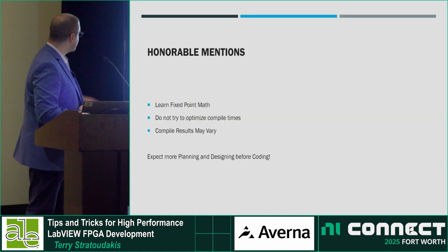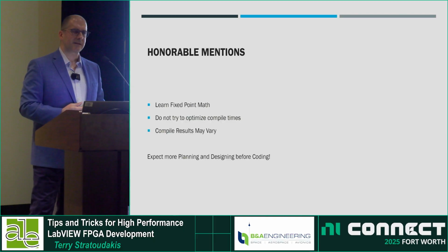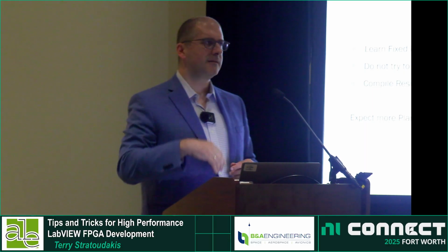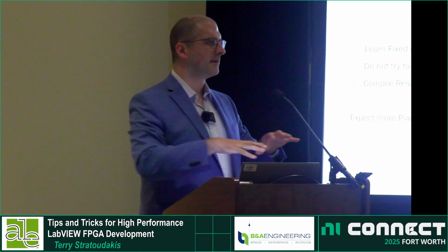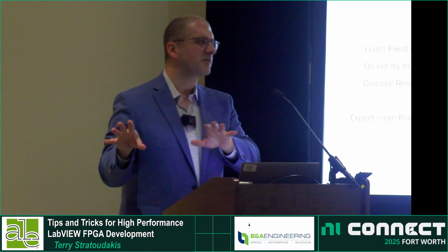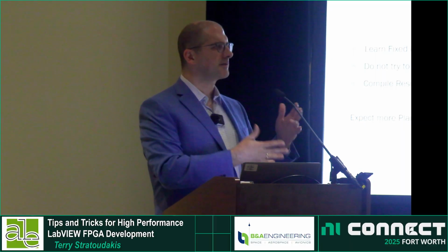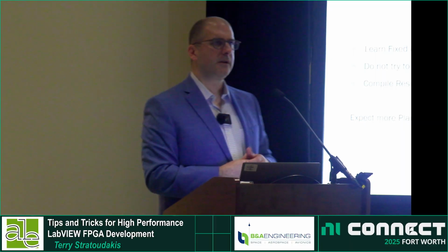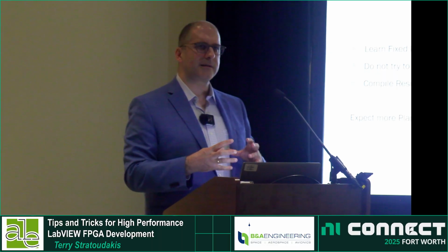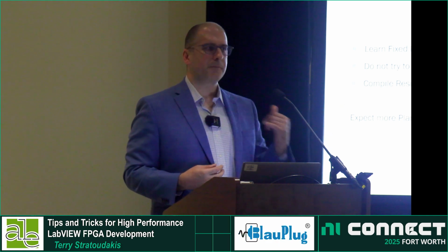And the last one over there is that compile results may vary. That could be scary. If I run the same compile, the same logic, on the chip, we can realize the same logic in different ways. Especially if the chip is not full, it can put the logic in different places and give you effectively the same clock rate, the same resources, the same everything. So you'll see different compile results, different compile utilization. It'll meet all your requirements, but you will see that sometimes.